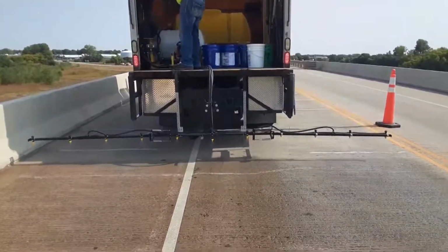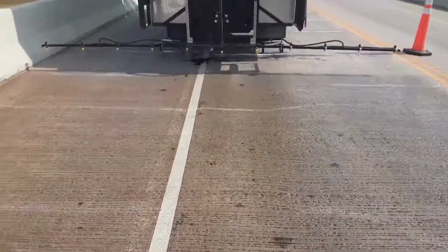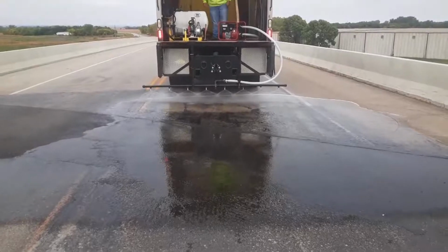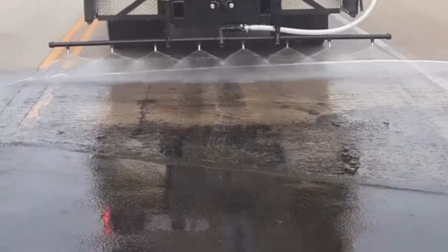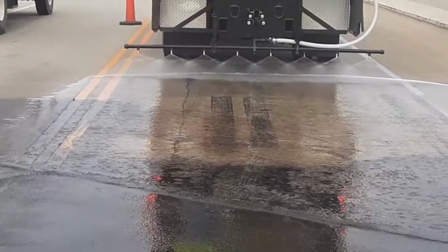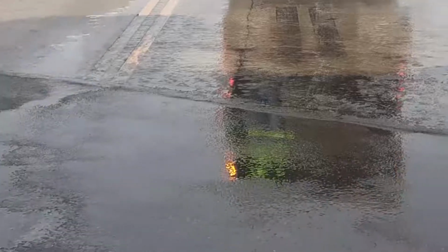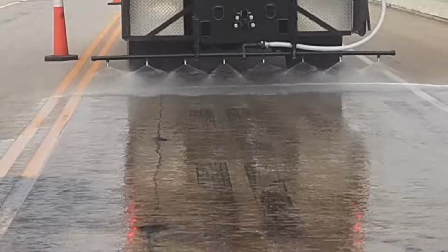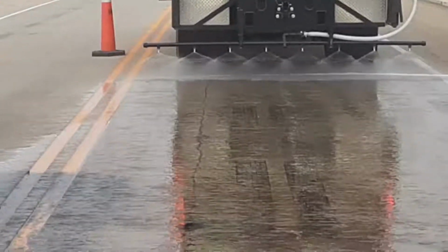And the application process that I'm going to show shortly is first you apply the waterproofing material. This material reacts with water. So we wait for this material to be applied, and then we water the structure. The reason why this is important is because this material has biochemical ingredients, has enzymes, and these enzymes need water to be activated for the first time. So what the DOT truck is doing here, in South Dakota, is the watering process. So they already applied the waterproofing agent, and now they are activating the material.